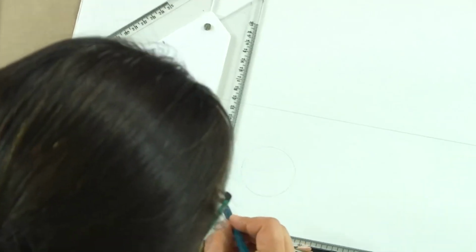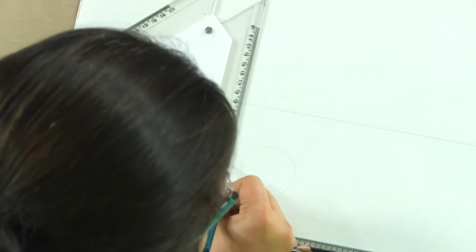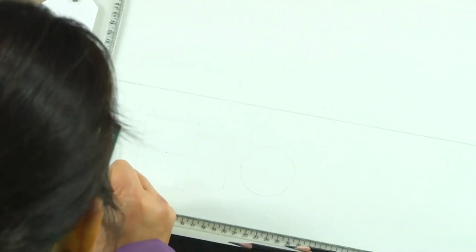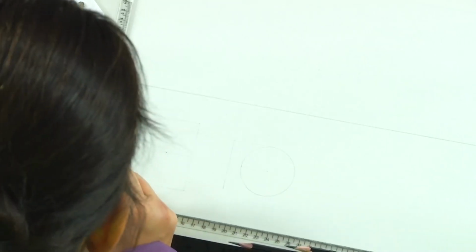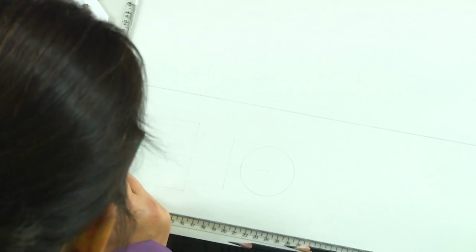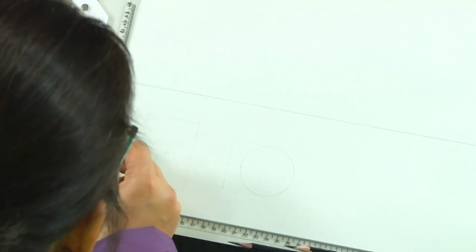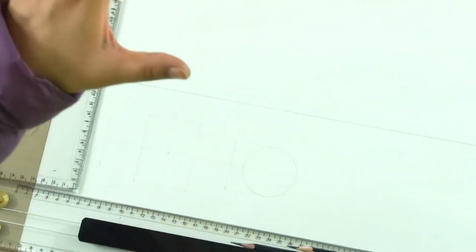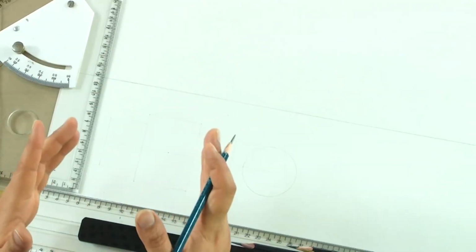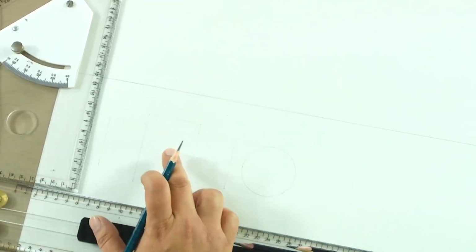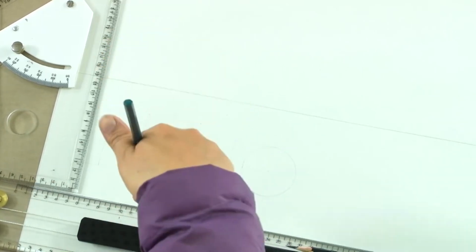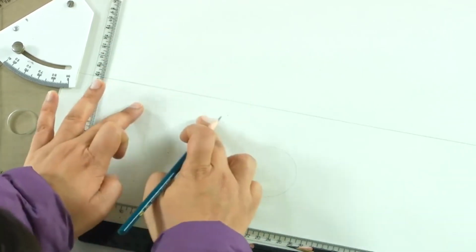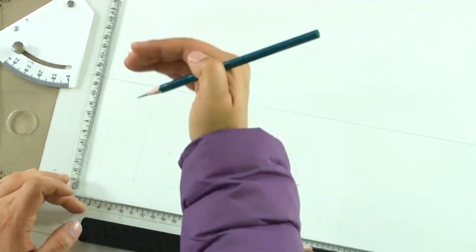So, this is the total length of the cylinder, and if we see it from the top, we will only be seeing a rectangle, because the fundamentals of our orthographic projections for solids will remain the same. What we are assuming right now is that there is a rectangular prism which is kept on the ground in such a way that its axis is perpendicular to HP and two of its faces are parallel to the VP.